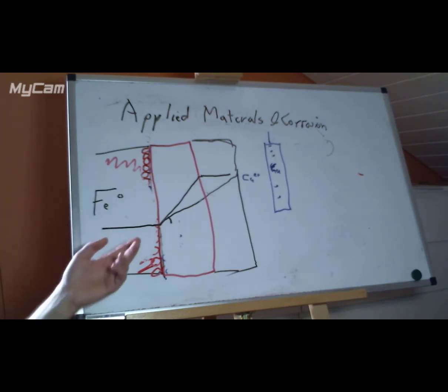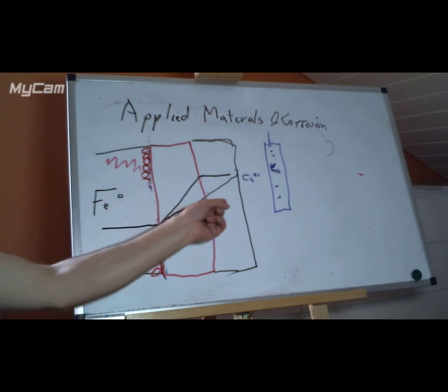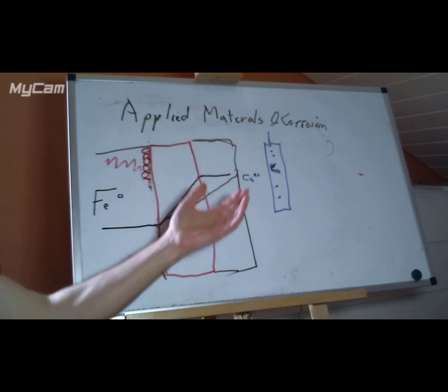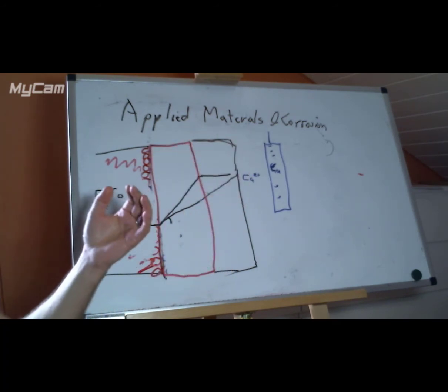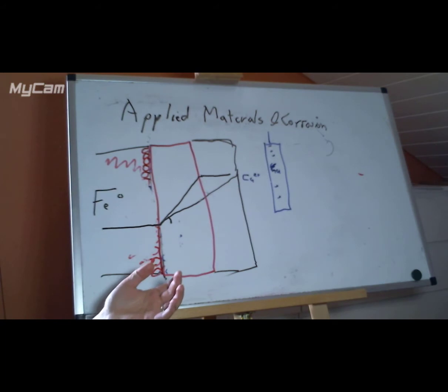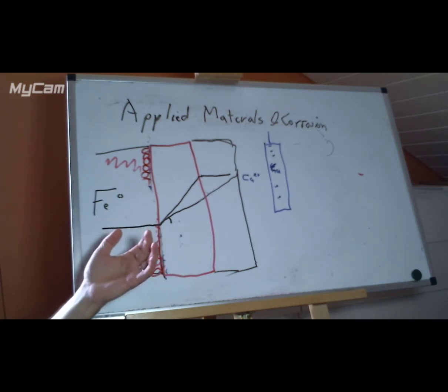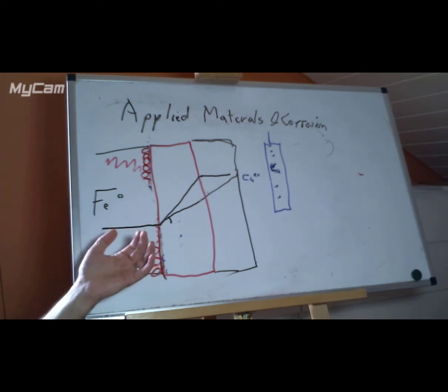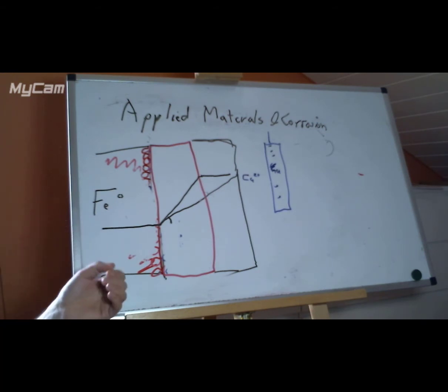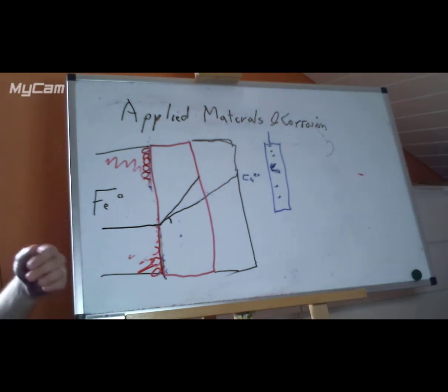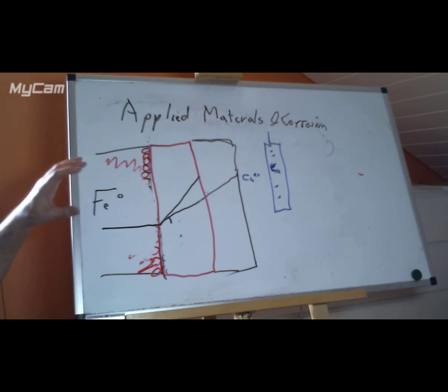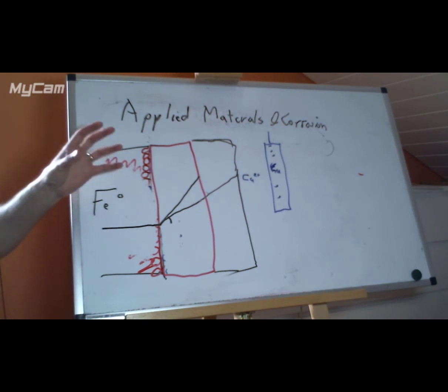And the other possibility is that the metal ions go all the way through and react with the oxygen on the outside. Obviously, both could happen, but it could be dominated by one of the two species. That's most likely to happen if one of them is way bigger than the other one. The metal ion is often the smaller of the two, but it isn't always.